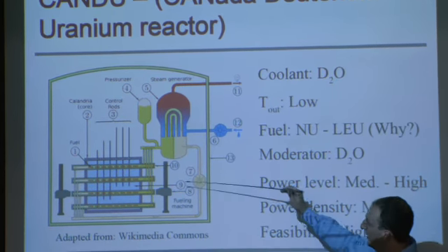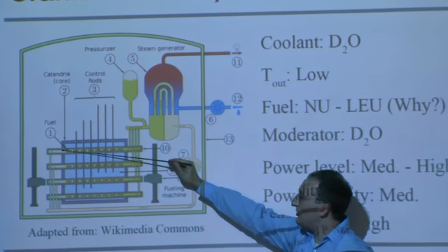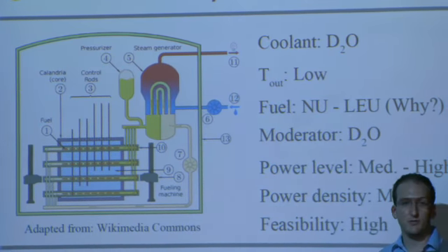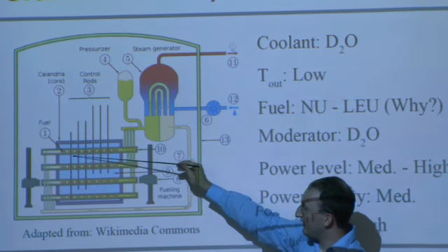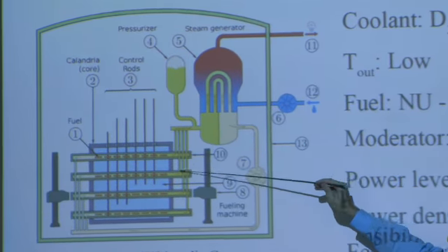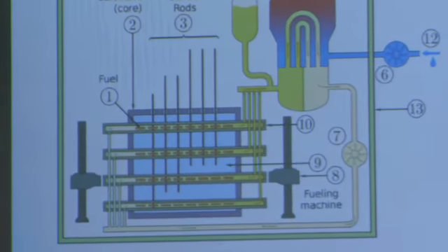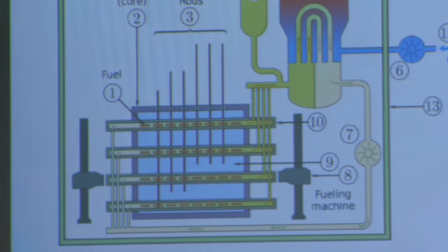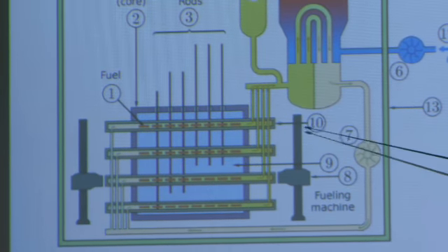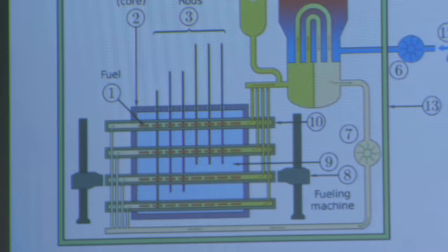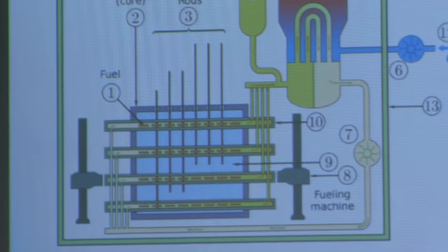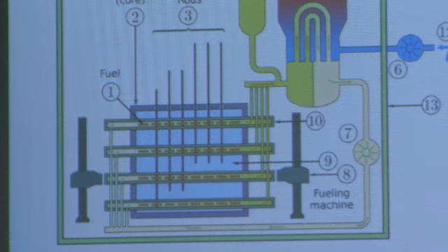I can just point this out. The coolant is in these tubes right here, which are called calandria tubes. This is actually the pressure boundary in the CANDU reactor. This moderator right here is unpressurized. It's also not heated directly. The calandria tubes are actually thermally insulated. So having that nice cool moderator as a giant heat sink is a nice safety system.